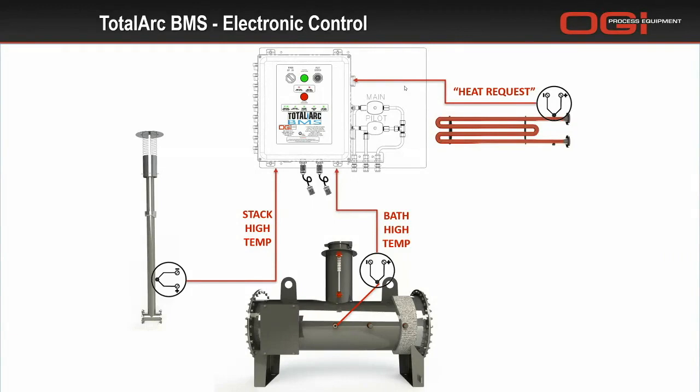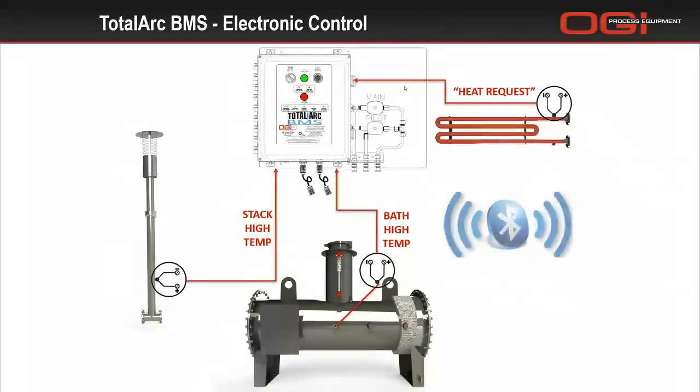With that, we enter our set points on an electronic module, and this data entry is actually done via Bluetooth through an application that can be obtained for both Android and Apple systems. And so it comes with a module you plug into these temperature modules, and it will allow you to adjust your set points. Operation is the same as we discussed previously, with the benefit that, being on an electronic system, you have much tighter control with regard to your set points and deadbands for the operation of the unit.